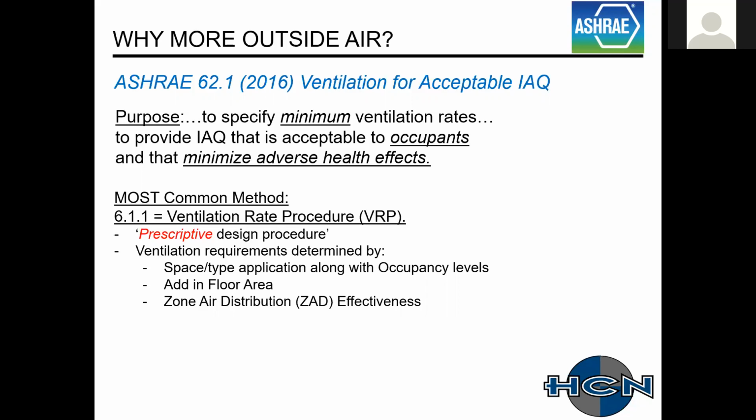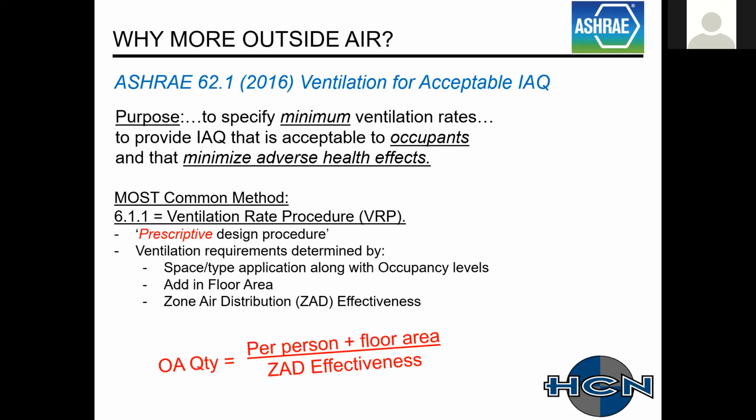And then you divide that by its own air distribution effectiveness. This takes into account how the air is distributed or supplied and returned from your space. There are different factors applied for supply at the ceiling, heating at the ceiling, et cetera. And then once again, this is a pretty common occurrence, or just everybody should be very aware of this.